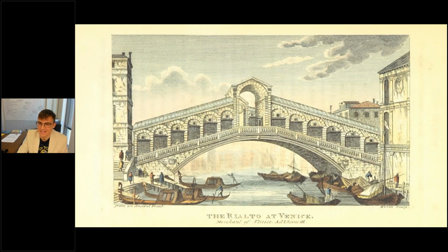specifically scan data that's captured through internal glazing. As a side note, something that causes a similar problem is thermal expansion and contraction of the facility that you're scanning. So I spoke with a team that was scanning Venice, and they would start their scanning early in the morning and end late in the afternoon. And the bridge that they started on and ended on actually changed shape due to thermal expansion during the day, and this caused problems for registration.